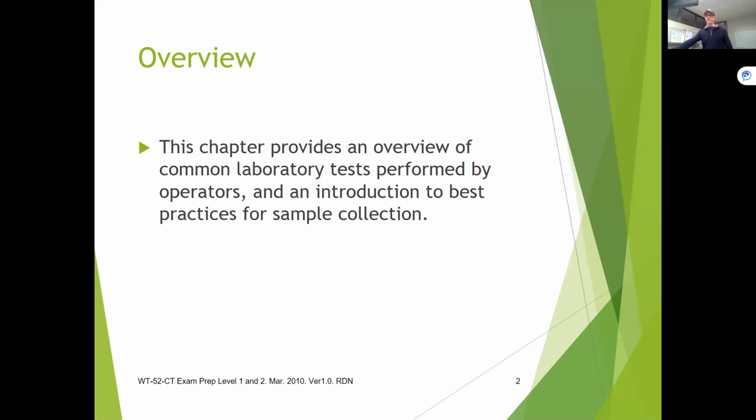We're testing for pH, anything that can change day to day. But anything big, like bacteriological samples, get sent to an accredited lab, which means it's specialized to do that test. And three times a year, we send out a scan, and it tests for everything: all the metals and pesticides and anything that's in the water. It gives us a good idea what's happening in our sources.